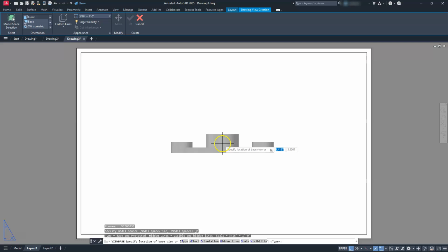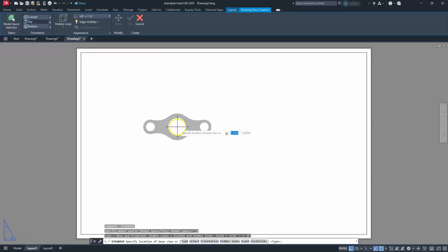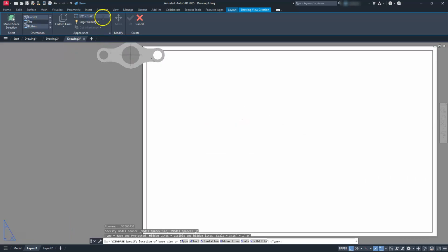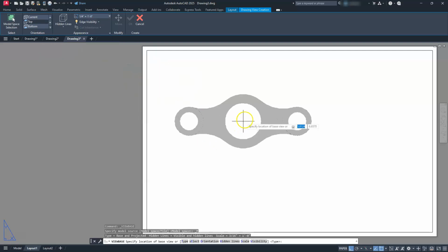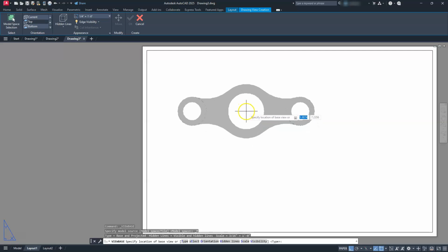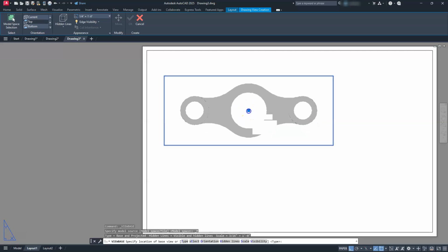So here's the view that I have. I'm just going to come up here and go find the word top. And there's my view. We can make this a little bit bigger, so it just depends on how you want to scale this up and down on the scale. Remember that as I go down on this scale, it's going to get bigger, and I'm using the English or imperial units. So I'm at 3/16 right now. Maybe if I want to go to 1/4 of an inch, that's what I have here. So I'll select here and go ahead and hit OK.